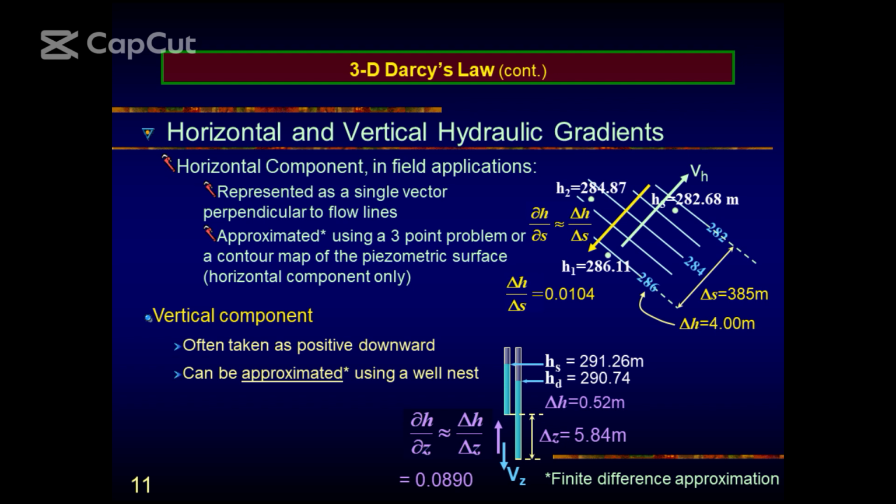Because it's the greatest decrease of... Go ahead. Is it the greatest decrease in head? Decrease. Okay. Or because it flows down, isn't it? What about the direction of the velocity? It goes down, isn't it? So the direction of the hydraulic gradient is in the same direction as that of the velocity. Okay? It's going down. So, but the gradient goes up.